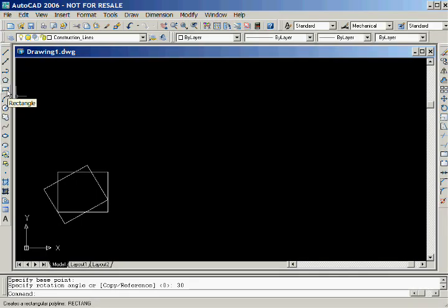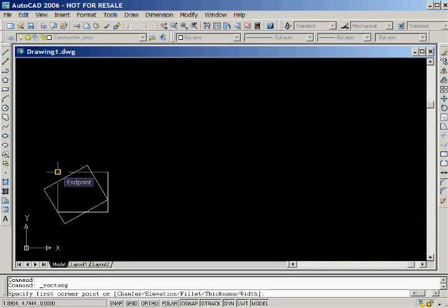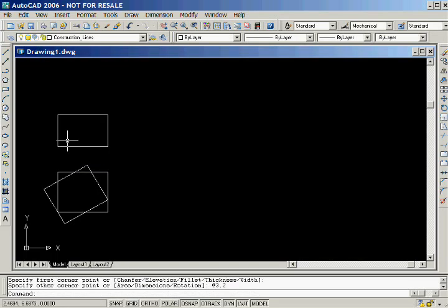We'll now begin to draw the top view of the V-block. After selecting the rectangle icon, we'll now locate the crosshairs over the corner of the front view in order to activate the Object Track Alignment feature. Now we'll position the crosshairs about 1.5 inches above the corner and then left-click the mouse, followed by keying in @3,2 in order to define the other corner of the rectangle.